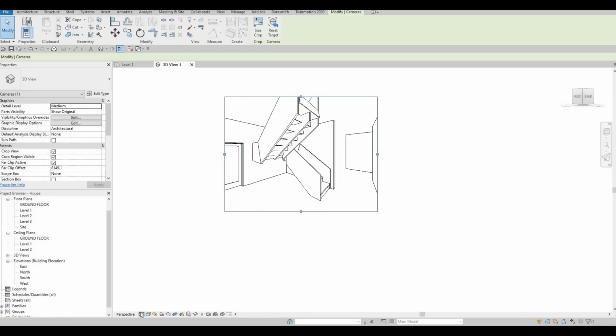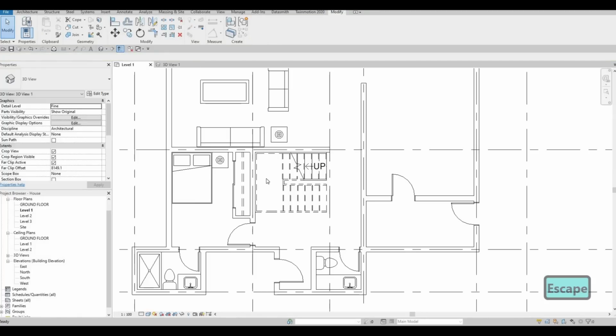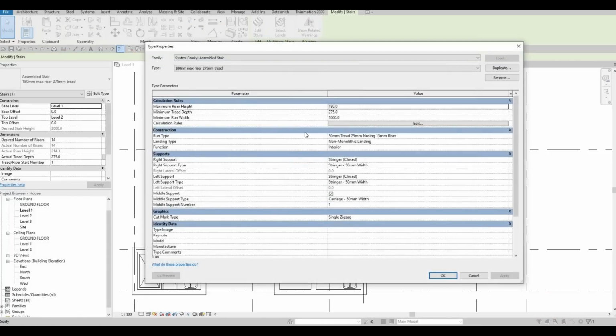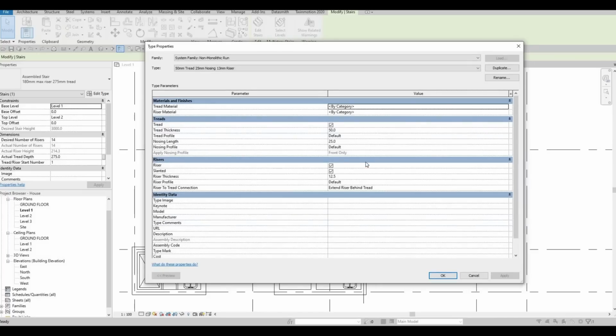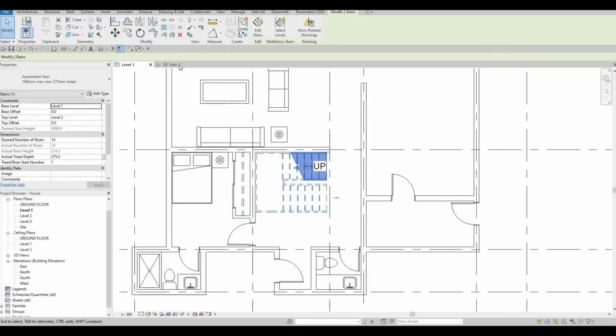An extra thing that we're gonna do is we're gonna remove. So I'm gonna select this, edit, and then we're going to go right here, run type, click on the 3 dotted lines, and then I'm going to uncheck the riser, and then here I'm going to uncheck that, apply, OK, and then OK.